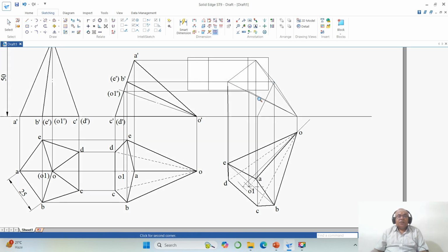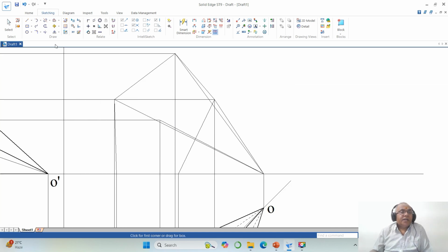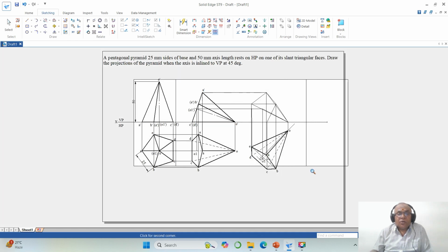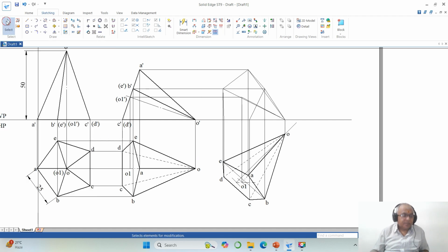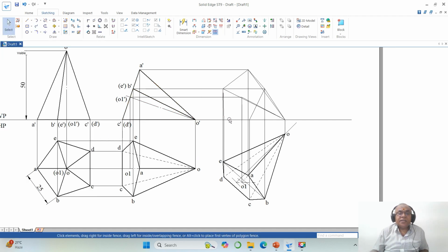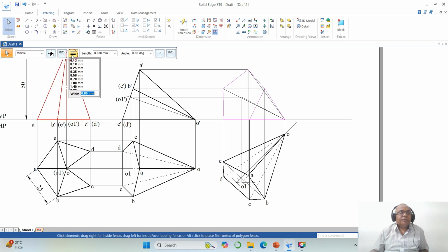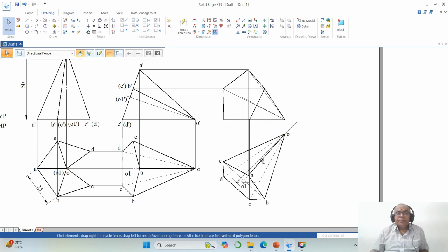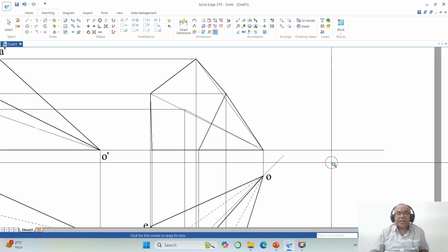So to do that, now we go for zoom window, and now you go to split this line till here. Okay, and then you split this line till here. So once you do that, you go to fit. So now all the exterior edges of the boundaries of the solids are visible. So you take this edge and this edge and this edge. Similarly, this edge is also visible. Okay, now you go to this and make it 0.5. So once you do that, now you have the clarity.